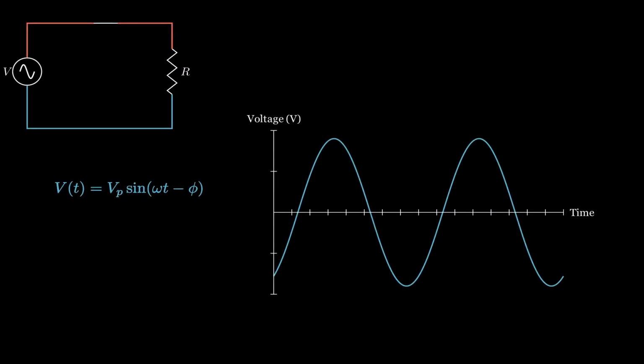Now, let's step into the real business, AC circuits. Let's go back to the same circuit and replace the DC source with an AC voltage source. In AC power systems, the voltage is sinusoidal. It has a peak value, which is simply the maximum and minimum values that the voltage keeps bouncing in between. Also, it has an angular frequency, which is given by 2π over T, where T is the periodic time. In most of the world, and where I live, T is 20 milliseconds, which corresponds to 50 Hz. In the US, for example, the frequency is 60 Hz, meaning the period is shorter.